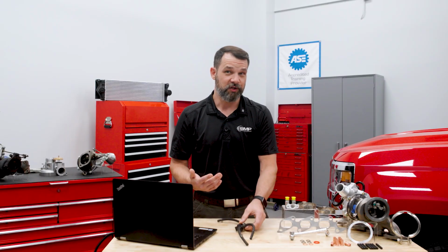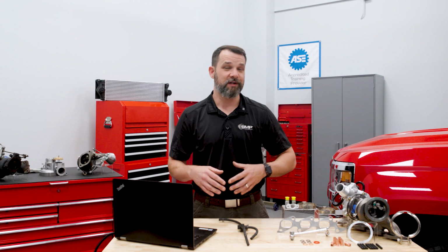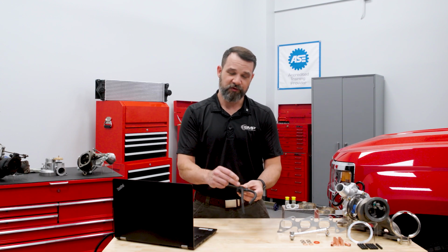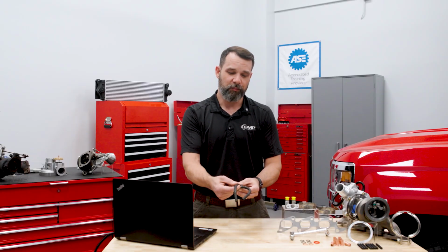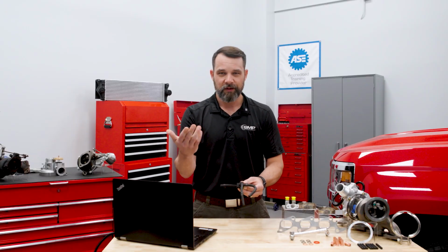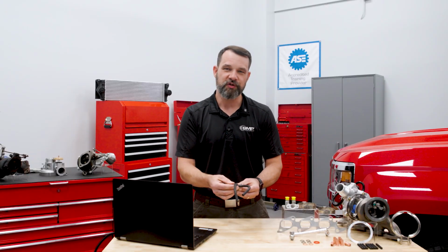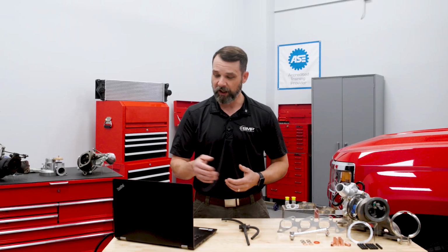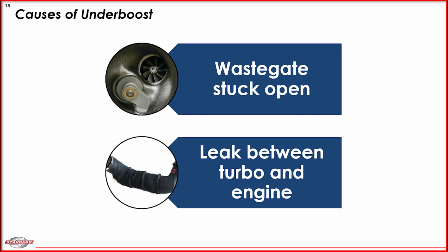And again, in that situation, we're not going to have to take the turbo off. We're not going to tear the whole system apart. It's just a simple fix. And in some cases, as long as there's no damage to the solenoid itself, we can probably just replace the hose. It's a simple, quick, very efficient fix. Makes your customer happy, gets the car turned out of the bay a lot quicker. All right, so back to the presentation here.